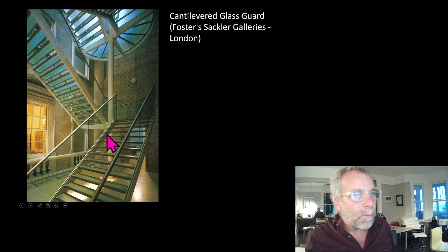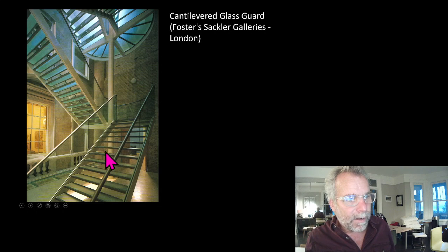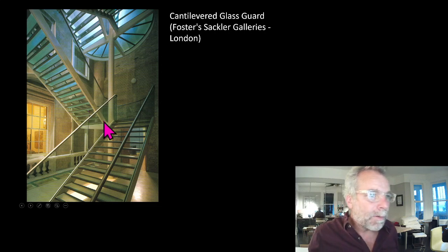So this is a switchback stair, as you can see, a very, very minimal switchback stair. This one has a landing support. There is obviously a valid load path without a landing support, and Shannon talked about that in some detail. So we could do this without a landing support, but look at how long this upper run is. This is a very high floor-to-floor height, and so this would be a very flexible stair if there wasn't a landing support. So in this particular project, landing support was provided.